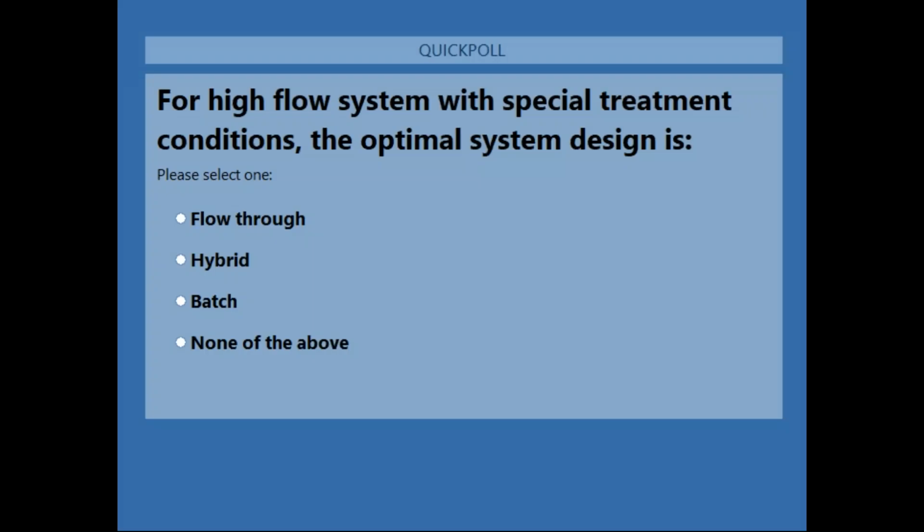The rate of mixing is important in achieving that CSTR reaction because it's really the rate of mixing that creates that well-mixed solution. Looking at the inside of a treatment vessel, waste comes into your system and then is directed down right into the mixer backwash here. These are your chemical injection ports up here, which also follow the inlet down. The reason to direct the waste to the bottom of the tank is to prevent what's referred to as short-circuiting, whereby your waste will enter the treatment tank and essentially go straight across right to your effluent. By driving the waste stream down into the mixer backwash with the reagent chemicals while you're adjusting, you end up with a very uniform mixture.